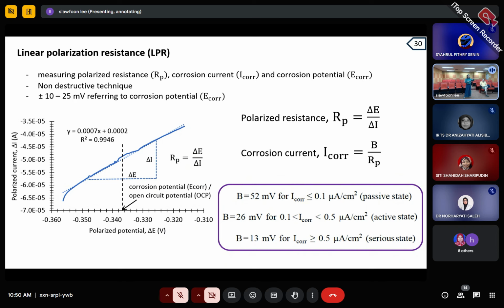It's called the open circuit potential. It's the potential where you can see there's a flow of atoms and ions to form the passive film. Of course, if you disturb a lot from this range, then you will cause corrosion. But if you stay within this small range to study what kind of potential the steel has, then it will not destroy the steel.